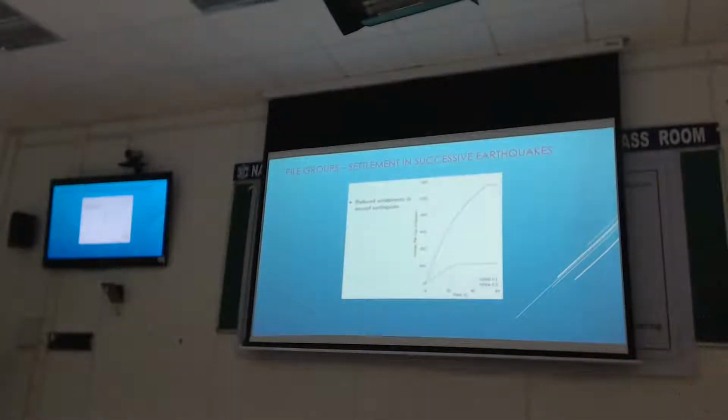So we are looking here at the pile cap settlements for a small earthquake and a large earthquake. We're starting from the earthquake time point of view when they started, but this blue earthquake was applied after the effects of earthquake one were finished. So the pore pressure buildup dissipates, and then we apply the second earthquake. So if you can see, we have a much slower rate of settlement compared to this one, right? Because it's a much bigger earthquake.